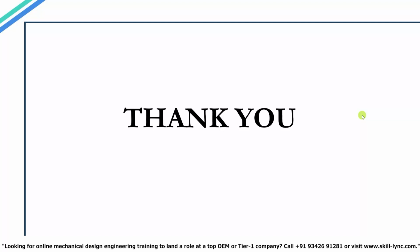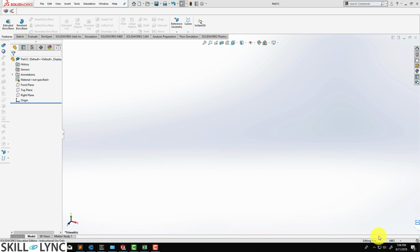Hey guys, hope you're all doing good. In this video, we are going to be modeling the final part, which is the crank. So let's get started with a new part and click on OK. Next, we are going to make sure that our unit systems are correct, MMGS, and looks like that's set up correctly. Then we are going to be selecting our front plane to start the sketch.